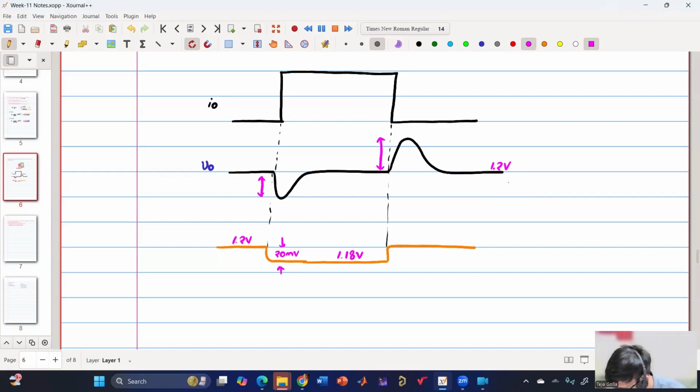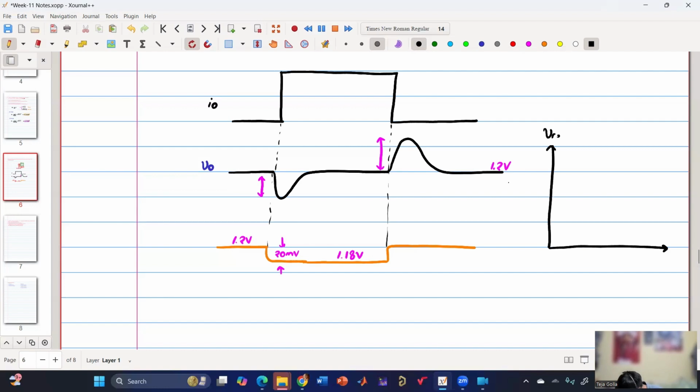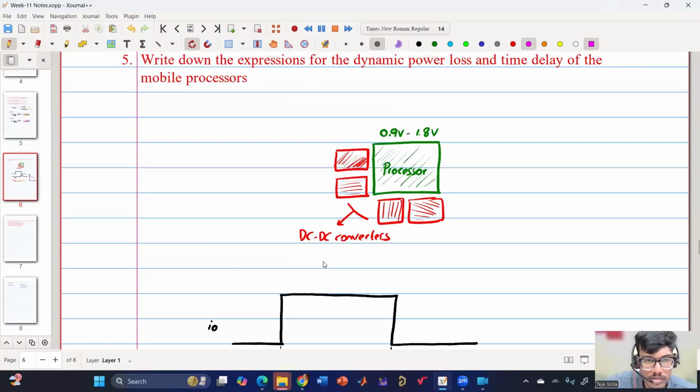So basically, if you draw the graph, so V reference at light load condition, it is V reference, but as the load increases, I am reducing my reference so that it will operate at a reduced voltage, reducing the power losses, increasing the efficiency. Also, my transient response can be improved because I need not bring the voltage all the way back to 1.2 volt. Instead, I can make it settle at a relatively lesser voltage. So is this concept clear?